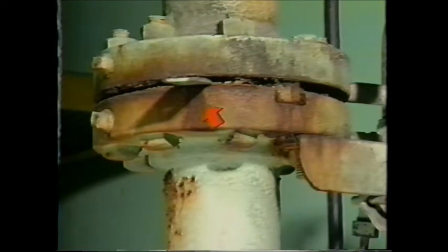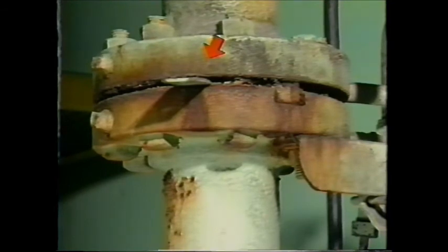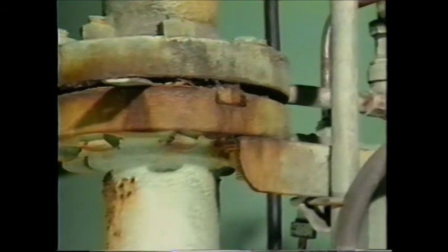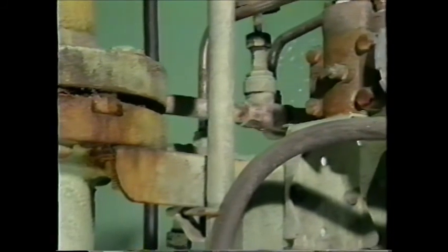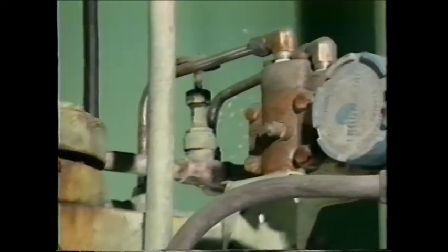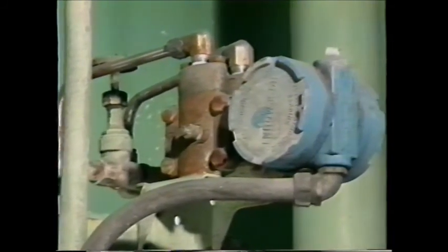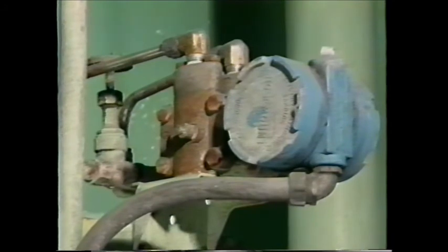Flow is directly proportional to the square root of the pressure drop across a fixed restriction. So, if an instrumentation system senses pressure upstream of this flow restriction and also downstream of the flow restriction, and then calculates the pressure drop, the differential pressure can be converted to a signal representing flow after compensating for the pressure and density of the fluid.